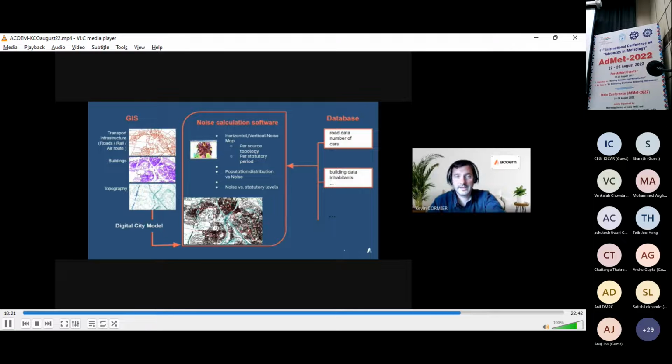That's it. The main challenges here are, first, set the expectation. The model and the resulting noise map only reflect the noise source included. Keep in mind what a strategic noise map aims for. Second, getting the relevant data from several stakeholders is a journey. You have to find the right compromise between the effort to get the exact data and the uncertainty of an estimate. The third challenge is to structure and organize the database very well, to automate the update, and to save effort in the refreshing process.